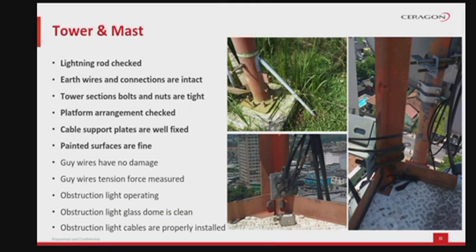Maintenance of the grounding system should begin with a visual inspection of all ground points and site components: fencing, shelters interior and exterior, air-conditioned units, generators, fuel tanks, transmission lines, and the tower itself. To reduce the potential for current overflow between separate ground planes, these points should all be electrically common. During a visual inspection, look for corrosion that could cause breaks in the grounding system or for evidence that the system has failed, such as flash burns or bluing marks on metal faces and grounding connections.